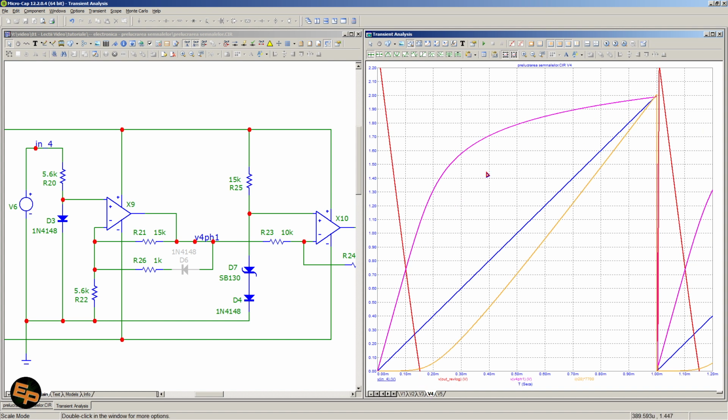We just care about having a sort of a curve, the output signal taking a bit of a curve. Okay, and let's say that this curve is not enough. If it's enough, then this is all that we need to do. If this is not enough and we want a more pronounced curve, then we must make the amplifier change its amplification factor based on the output voltage, in the sense of reducing the amplification factor if the output voltage goes above a certain level.